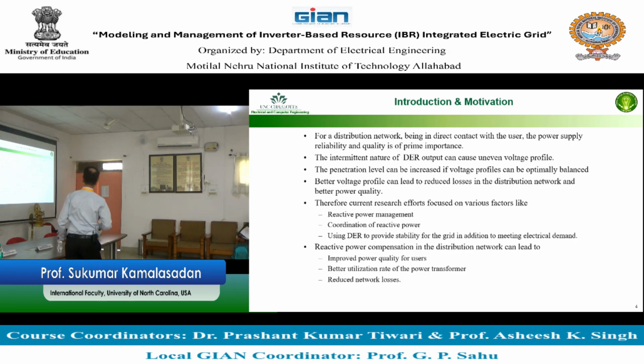Reactive power compensation in the distribution network leads to reduced network losses, better utilization rate of the power transformer, and improves power quality for the users. Because reactive power is directly related to power factor improvement and power quality improvement.